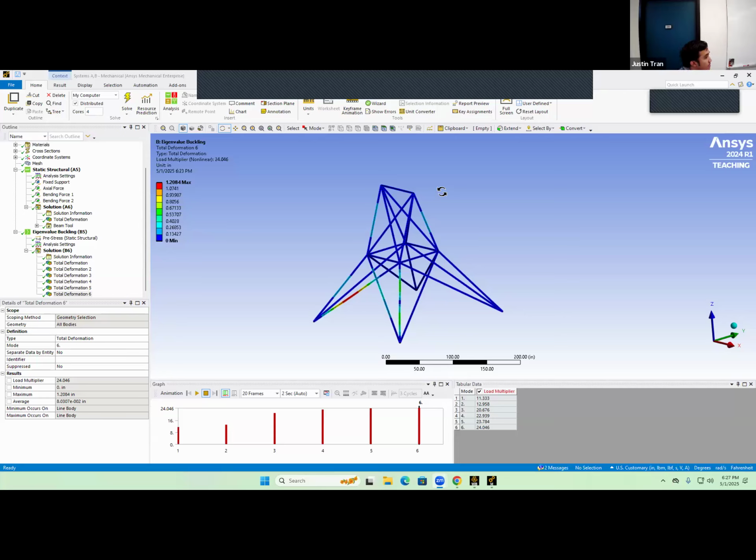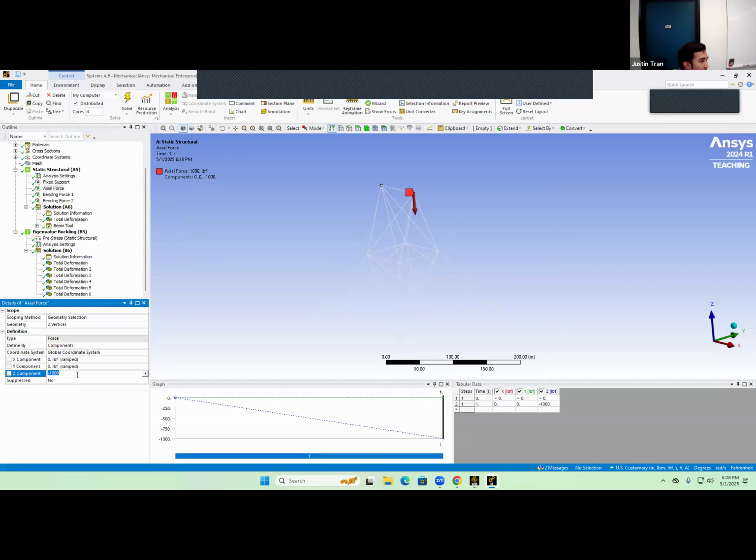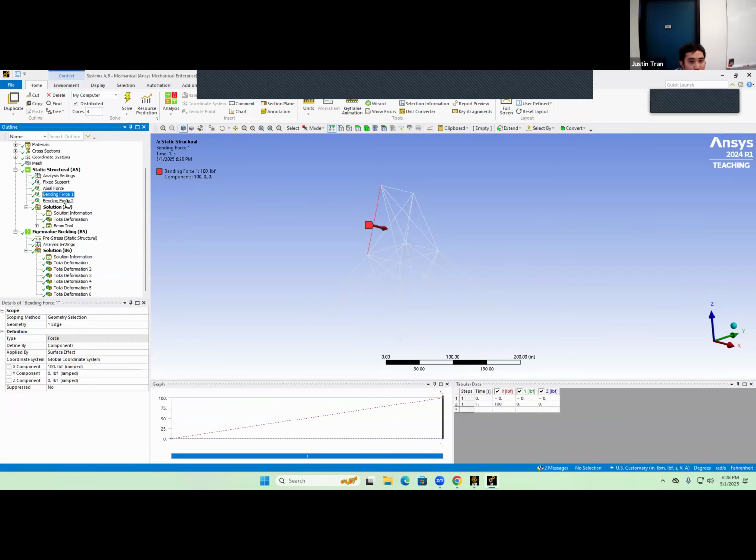These are different simulations based on the number they give you. To produce those, for this one in particular, they multiplied all the modes by 11, and then they highlighted which parts of the structure will fail first. If you actually want to test it out, you would go back to your modes here and multiply this mode by 11.3, and the same thing for these ones too.